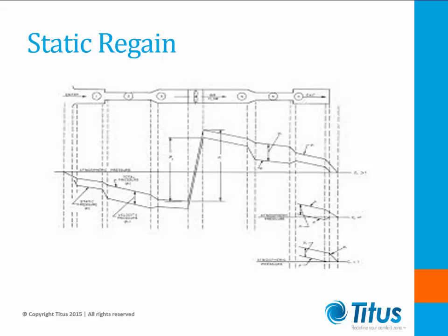Static regain is mainly employed in large, high-velocity systems. The higher velocity provides adequate potential static regain to make the design and the added ductwork cost-effective. Due to the higher velocities, the ducts generally cannot be adjacent directly to or directly above occupied spaces. Rooms and spaces with large volumes or high ceilings provide adequate distance, though, for the sound generated by higher velocities in the ductwork to dissipate before reaching the occupants. Such spaces would be athletic stadiums, airports, and conference centers.